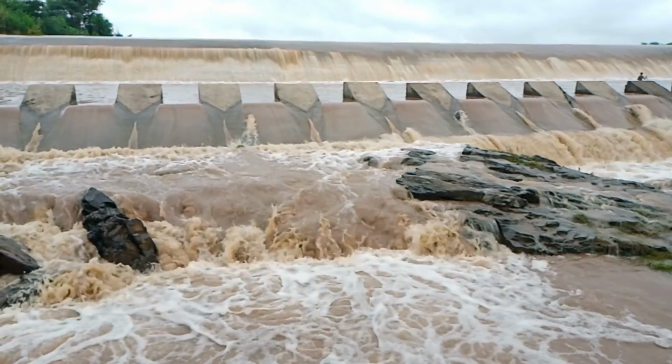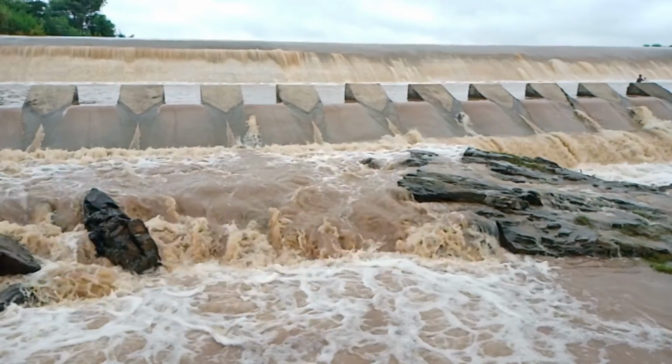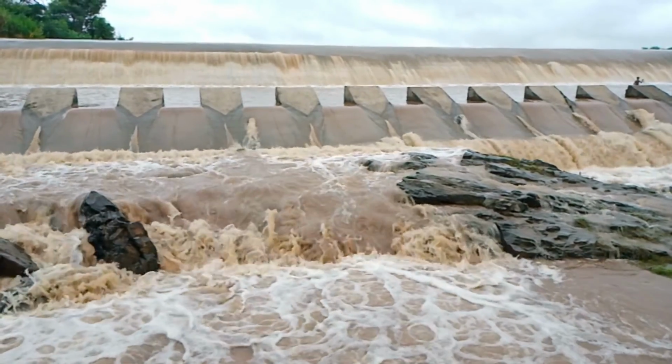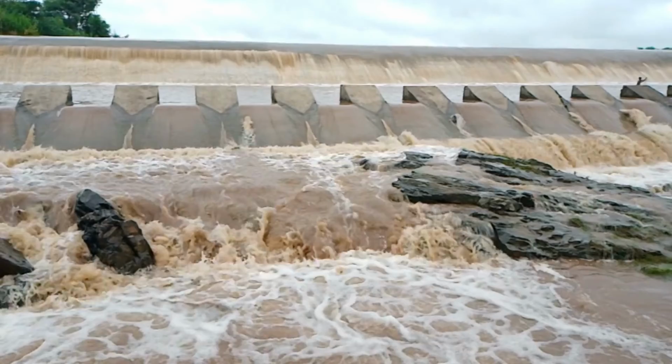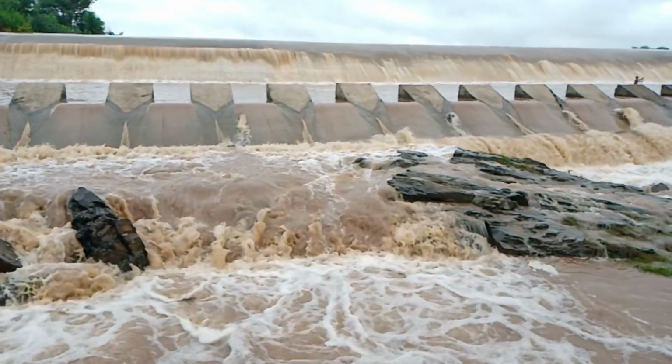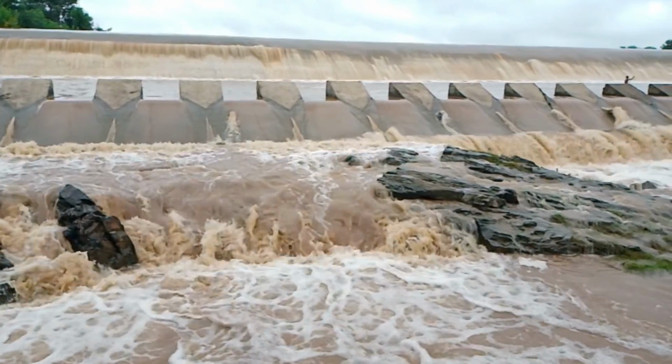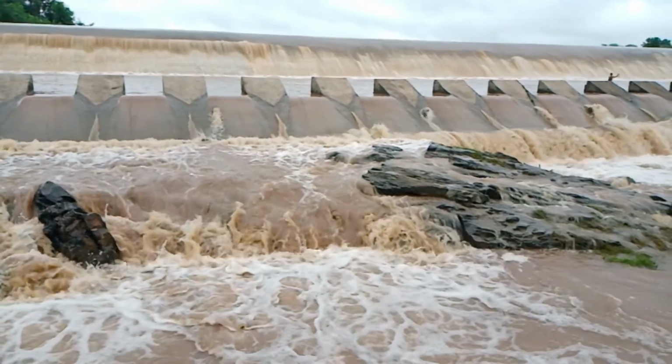Now, I will talk about the types of contaminants that are filtered out by both rapid and slow sand filters. For the rapid sand filter, it is effective at removing coagulation and flocculation solid particles and impurity sediment in the wastewater during pre-treatment. On top of that, the rapid sand filter can also remove turbidity of the wastewater.